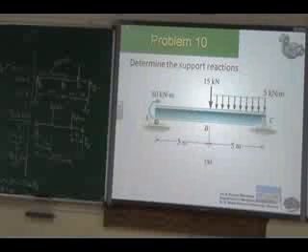Moment, that is the moment. Applied moment. You have an applied moment, one applied point load and one UDL. The point A is simply supported or roller regardless, so you cannot allow it to move in the y direction. It can freely move in the x direction. So only one reaction at point A. Point B is hinged. So no movement, no translation in x as well as y direction. So two reactions are there. Hinged, two reactions. Simply supported, one reaction.